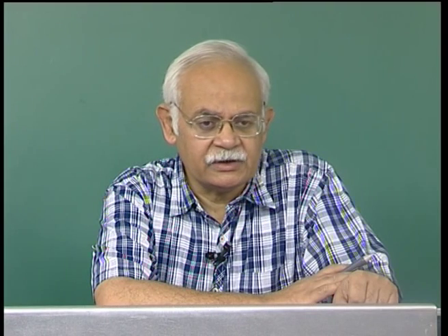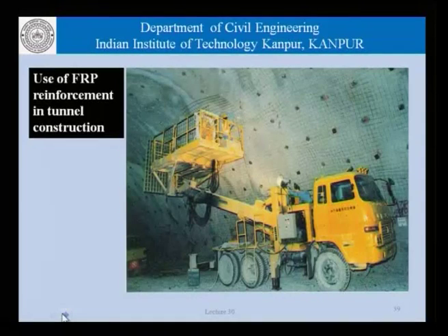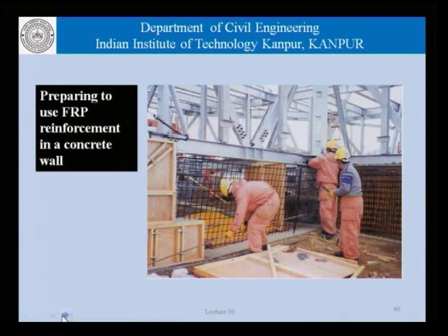Now, continuing from the last discussion, let us look at some more field applications of CFRM. Here we are using CFRM in tunnel construction. We can see a net which has been placed using these bolts to hold a lining which is going to be applied on the tunnel. Similarly, here we are looking at FRP reinforcement being placed, which again is a grid as shown here, for the reinforcement in a concrete wall.